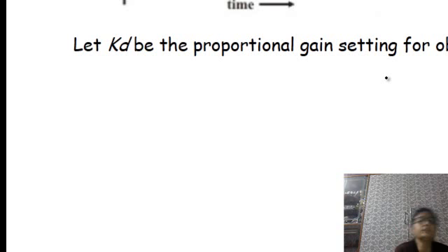And as we all know, constant oscillation is not acceptable for a real system. So another model proposed by Harriot is the damped oscillation method, where a damped oscillation is allowed. The ultimate method may not be applicable for processes where sustained oscillation may not be permitted.